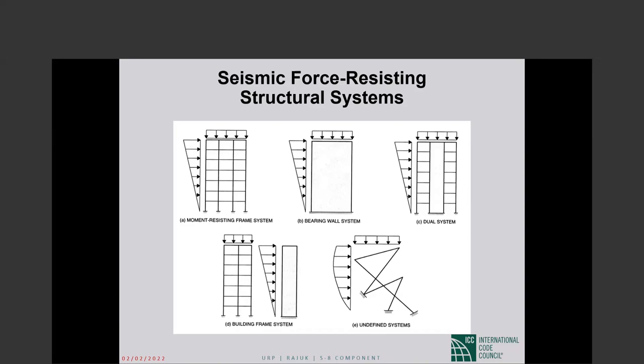You have to do an interactive analysis that will show that the distribution in the first story is 95% going to the shear wall, 5% going to the frame. But in the 30th story, it is the other way around, 95% going to the frames and 5% to the shear walls. You have to design on that basis. Okay. And that then leads to the second condition.